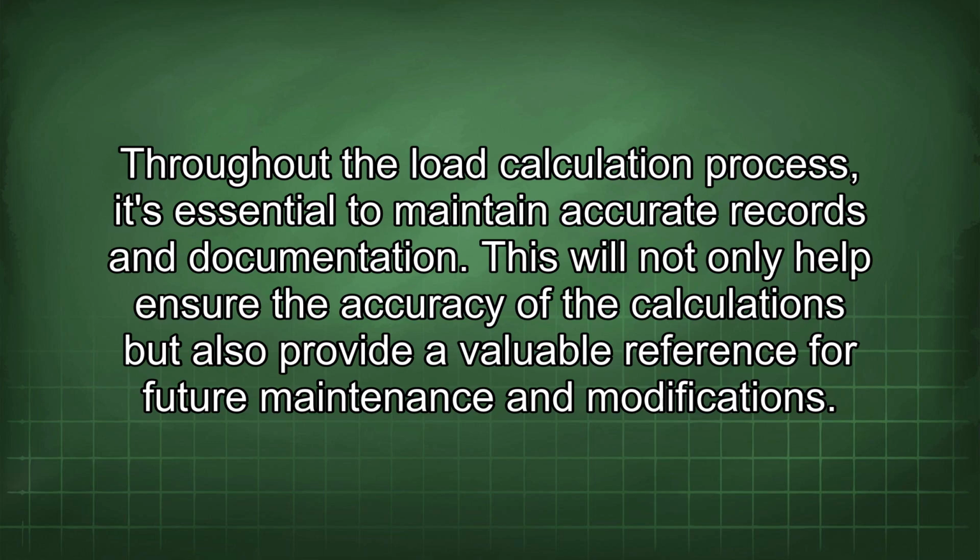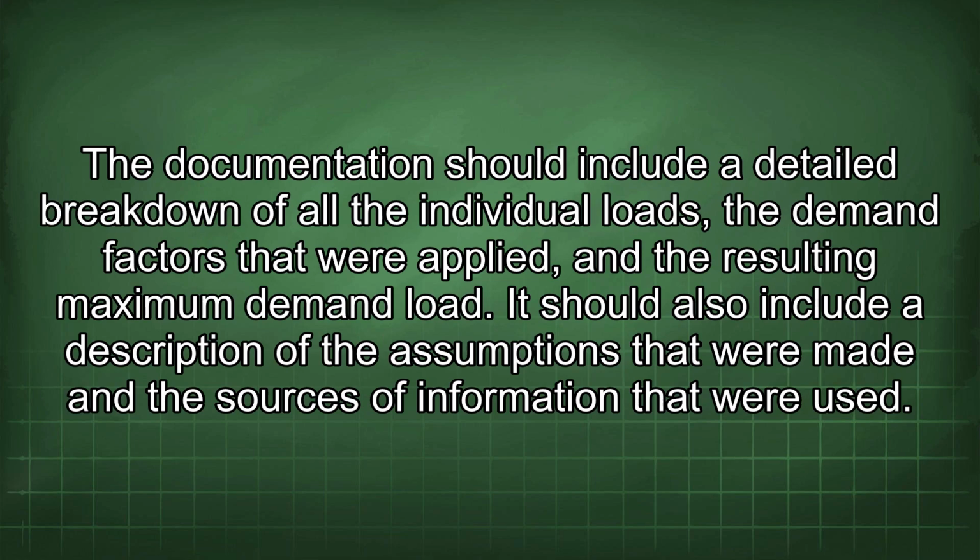This will not only help ensure the accuracy of the calculations, but also provide a valuable reference for future maintenance and modifications. The documentation should include a detailed breakdown of all the individual loads, the demand factors that were applied, and the resulting maximum demand load. It should also include a description of the assumptions that were made and the sources of information that were used.